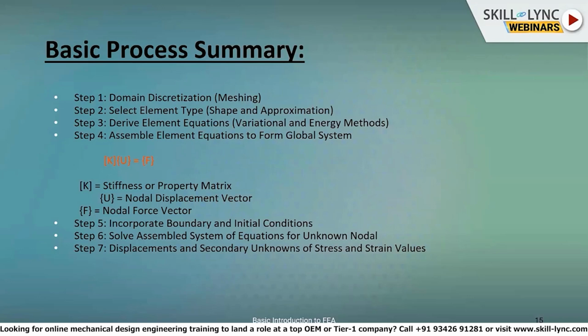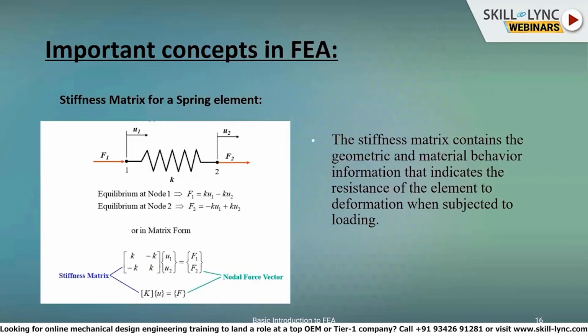Then compute the non-singular global stiffness matrix, then define the external load and solve the static equilibrium equations, compute the displacement vector, and after that compute the other outputs like stress, strain, contact pressure and all other things. You can definitely go ahead and use that. Then